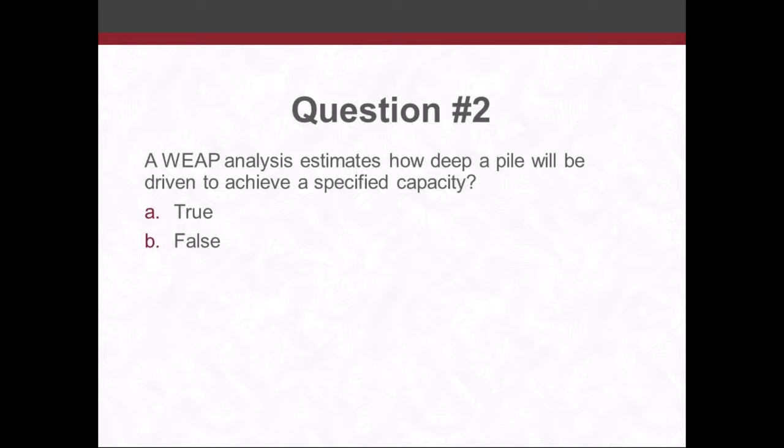Okay, question 2. WEAP analysis estimates how deep a pile would be driven to achieve a specified capacity. The answer there is false. It's going to estimate a blow count to achieve a specified capacity, as well as the stresses.